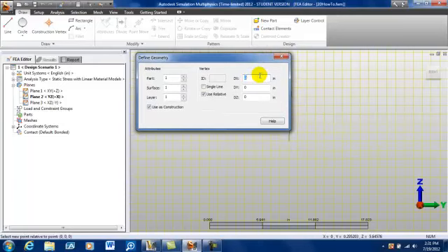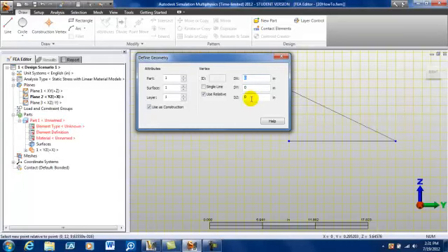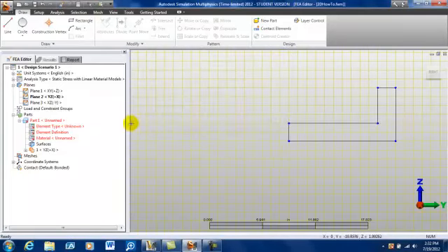For Y, I'm going to go dy. Let's go 12 inches in the Y direction. I'm going to go 6 inches in Z. I'm going to go minus 2 inches in Y. Minus 4 inches in Z. And then I'm going to go, let's see, I believe it's minus 10 inches in Y. And then just close off my L shape here. All right, so that's my part.